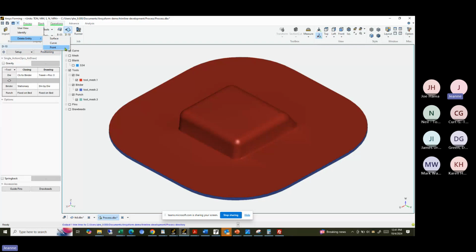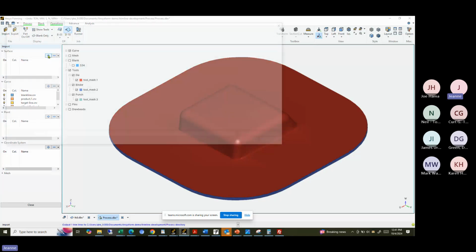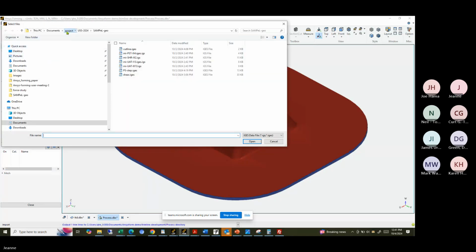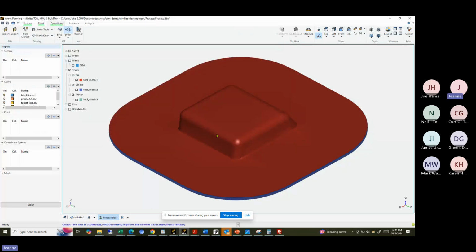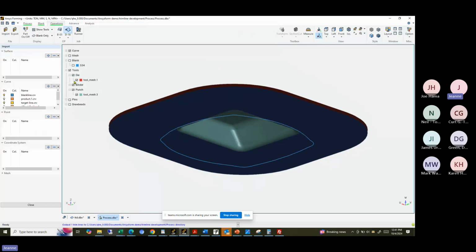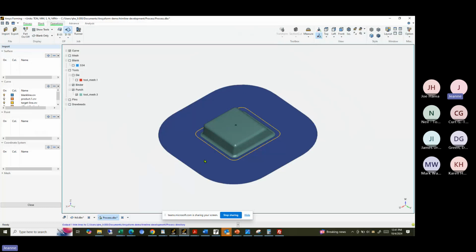The reason we do that is sometimes they have way too many surfaces, like the lower tool, lower punch, they have all the nitrogen cylinders and also all the screws and dowels, and those really slow down the simulation. So very often you have to end up cleaning the surfaces. Just simply delete them. So you go here, delete is a new function added.